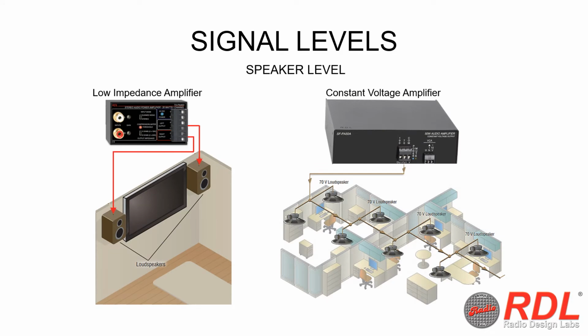The third and highest level signals are speaker level. Speaker level signals are post-amplification, meaning an amplifier is used to elevate or boost a line level signal to a strength needed to power speakers or headphones. Available in a variety of power levels from very low to high, specific amplifiers are chosen to support each audio system's needs. Therefore, speaker level signals can be very high in voltage and require specific cables for transferring these signals.